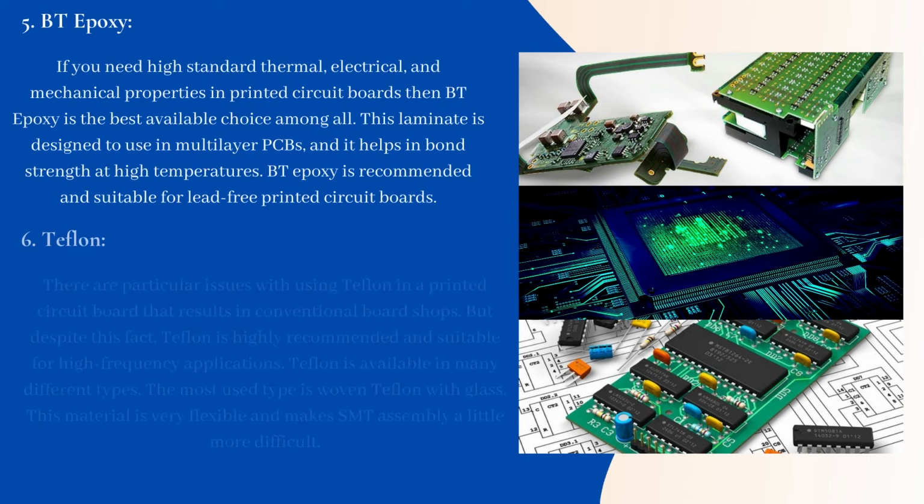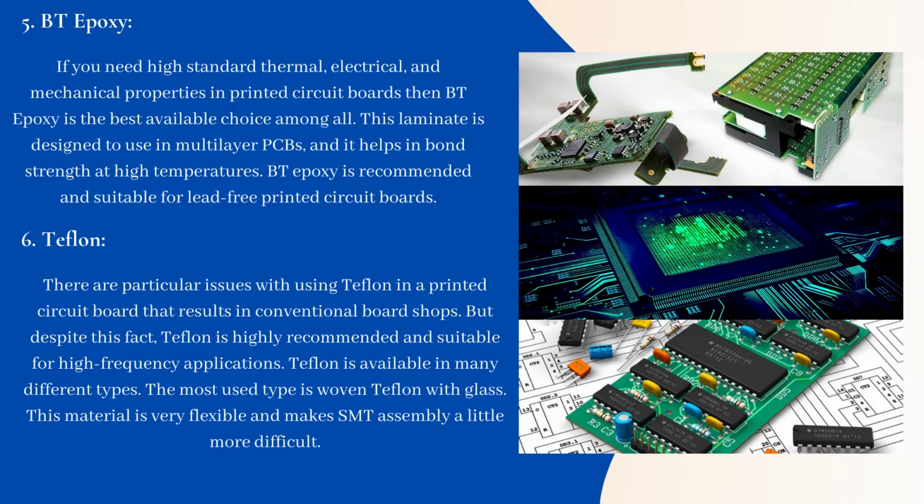BT epoxy. If you need high standard thermal, electrical, and mechanical properties in printed circuit boards, then BT epoxy is the best available choice among all. This laminate is designed for use in multilayer PCBs, and it helps in bond strength at high temperatures. BT epoxy is recommended and suitable for lead-free printed circuit boards.